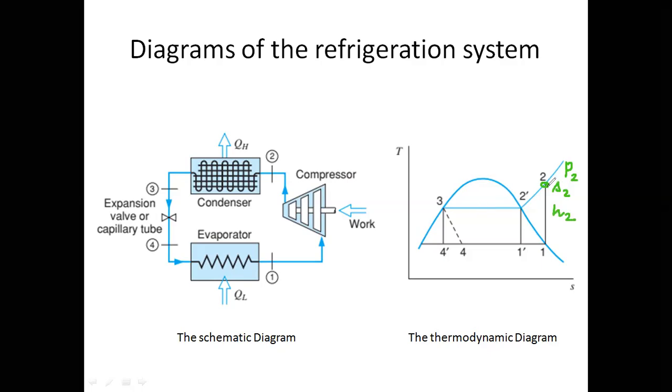So how to calculate the value? This is in the superheated vapor table. We can verify that also. The S2 value is 1.7395, and since this is an isentropic process from a lower pressure, it must be in the superheated vapor, but still we can verify from the value of Sg at 40 degrees centigrade.